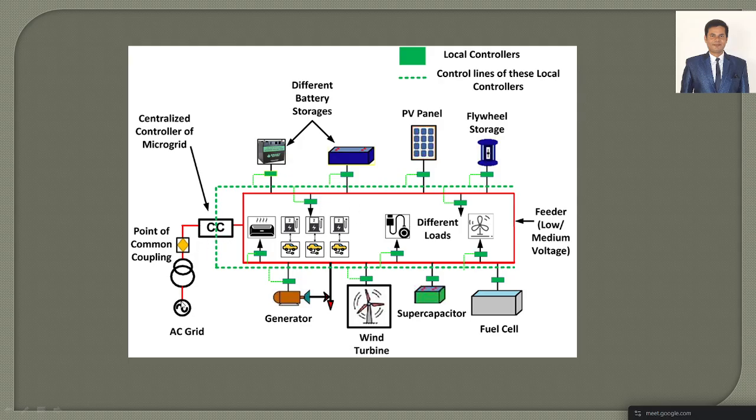So power is also coming from the other grids, from another grid we are also getting power. So if this grid fails, this coupling point will be disconnected, and if power is not generating from here, the battery will try to give the power to your charging stations, right? We also have the diesel generators. So it will try to change the loads, right? An automatic load changer will be there, right? It will change the load connected to this grid and connect it to the diesel generator, they will have incorporated the system like that. Okay, so that is one of the major components, the point of coupling, right? I'm talking about the point of common coupling as one of the major components.